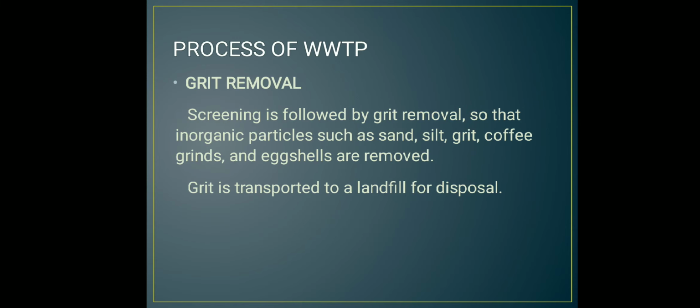Grit removal. Screening is followed by grit removal so that inorganic particles such as sand, silt, grit, coffee grounds, and eggshells are removed. Grit is transported to a landfill for disposal.